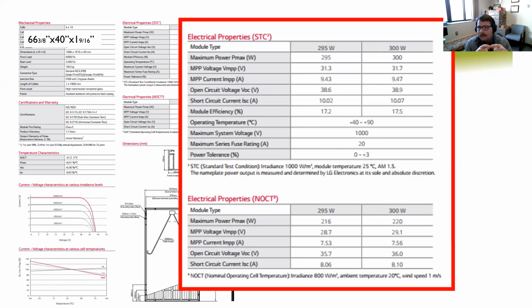And that's essentially one of the reasons why they're going to cut them into pieces rather than having larger cells. And they're beginning to cut them into smaller and smaller pieces to work out the voltage and the things that they want. So those are some of the reasons. The monocrystalline, it's very tough to grow a very large crystal, so they grow those crystals and then slice them, and that's about as big as they can get, or they want to get, I suppose, from an economic reason. They limit that size to about 6 inches by 6 inches.